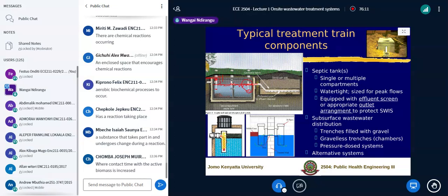And so being controlled, it means that there can be no water going out or coming in during that process. Because we talk about retention time or detention time. When you design this tank, you design it to hold water for a particular average detention time. So if water goes in or out other than to the designated points, then you cannot assure that.